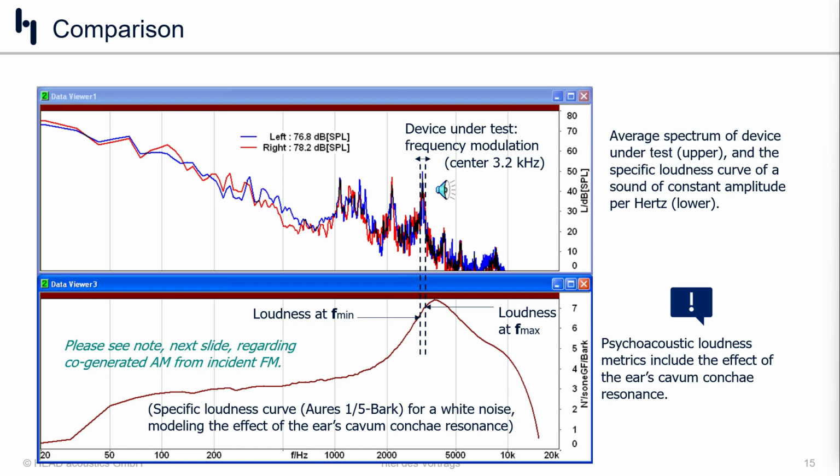This is a very old example we've used forever, 35 years plus in head acoustics, where there is one tone that is at the same level as a tone at a somewhat lower frequency, but it is much more noticeable and more annoying. The reason being that it is farther up on the resonance slope, which is calculated by the loudness metric. So if it happens to be frequency modulated and is going up and down in frequency, it is also climbing and falling on the hill of the resonance. So there is an amplitude modulation that gets generated by the HRTF, causing a stronger pattern of greater annoyance to a human being. So here is that sound.